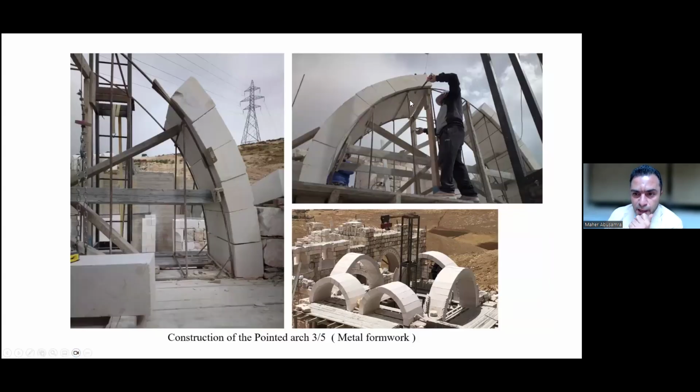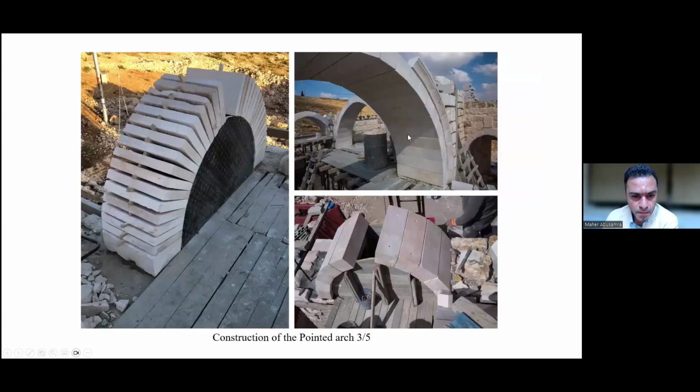Here we use a very, very light formwork, which is only a steel bar. We put 2 of them and construct these big pieces of arch. And we have this manual crane, electrical crane. After we release and put the keystone at the middle, we can easily remove this formwork. So it's not expensive, because even the steel bars we can reuse again.